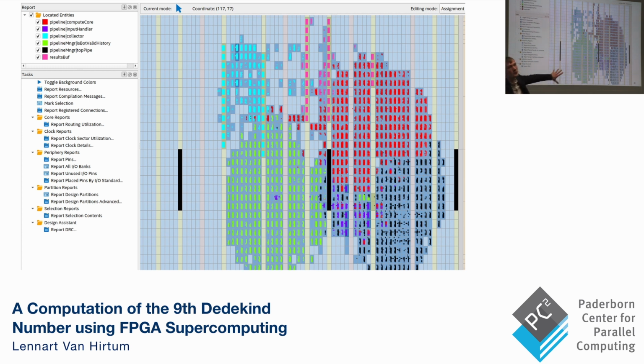For those of you who are unaware of what FPGAs look like, FPGAs are basically a giant grid of logic cells. The most common ones are these blue ones here. They are the normal computation cells. These just contain lookup tables. Basically, they're just gates. You can say, okay, this one does an AND operation, this one does an OR operation, this one adds 2 numbers, like really small operations. Then these yellow ones are memory blocks, which is how you can recognize the input FIFO and the result collector.